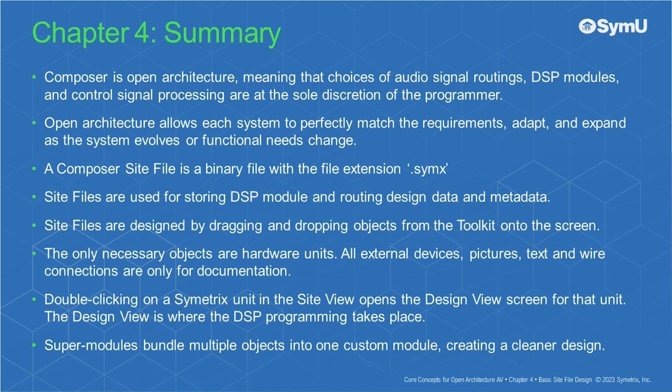Site files are used for storing DSP module and routing design data and metadata. Site files are designed by dragging and dropping objects from the toolkit onto the screen. The only necessary objects are hardware units. All external devices, pictures, text, and wire connections are only for documentation.